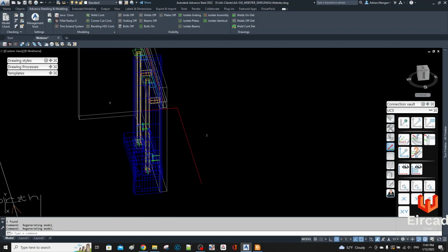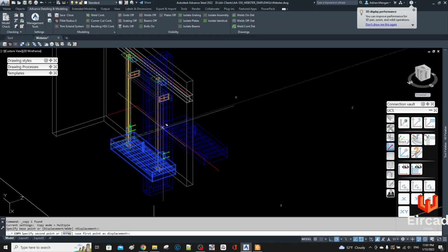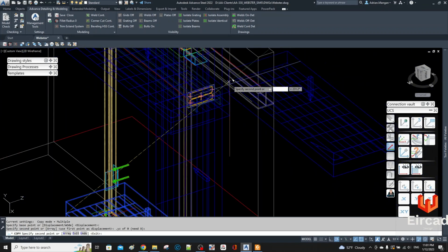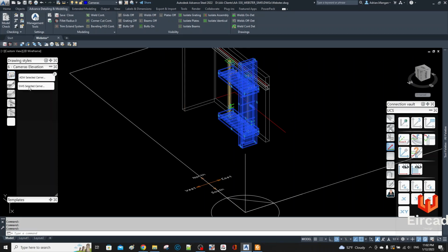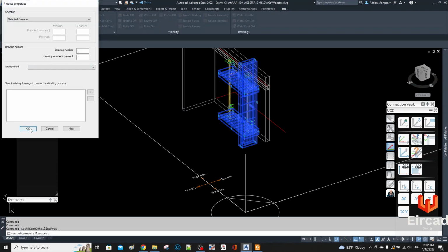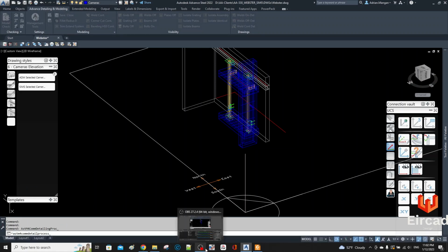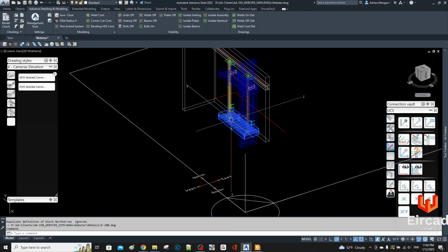I don't know if I'll make that a section. I might change that one. I'm going to copy this up in the Y direction and to center this beam. And then we can just pick the 3 of these and come here. What do I want to number that? E100. So I have the E on the sheet, so I'm going to call it 100. E100.